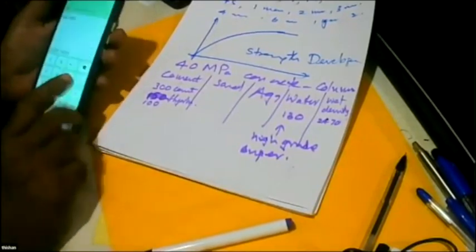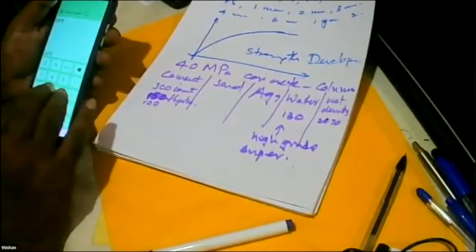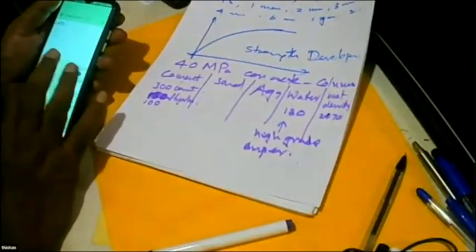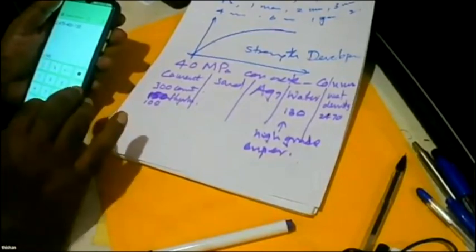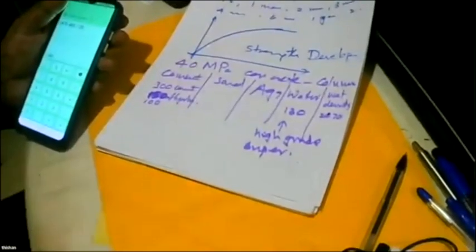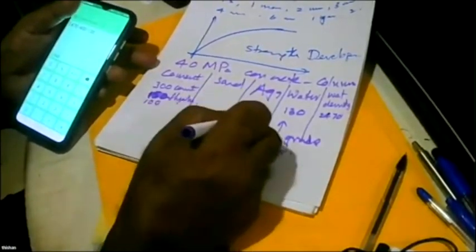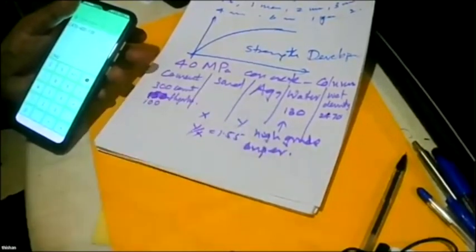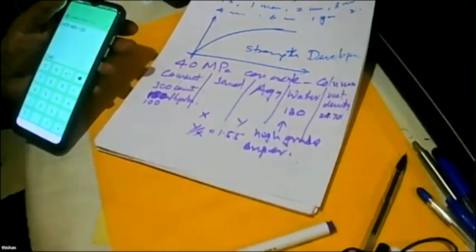Now I'm going to look at numbers. 2470 minus 400 minus 130. Now this is in a column, so I have to pump. So I am going to use Y over X ratio as 1.5. I'd like to get high strength also, so I don't like to use too much sand. I like a little less sand, but at the same time I'm a little restricted.